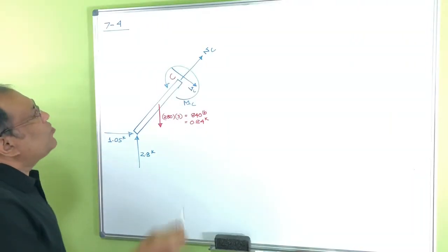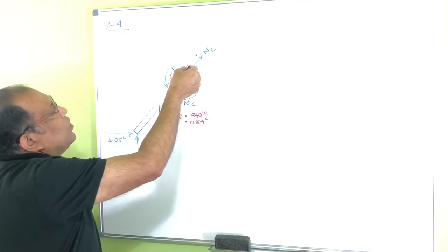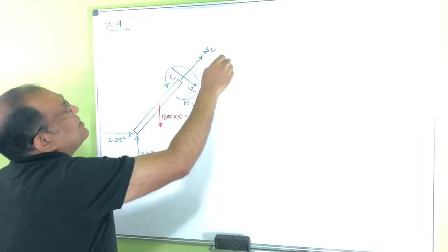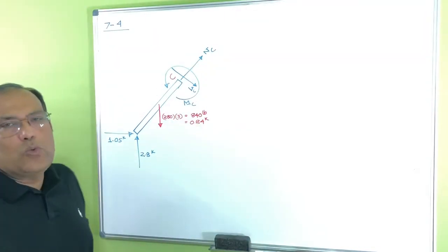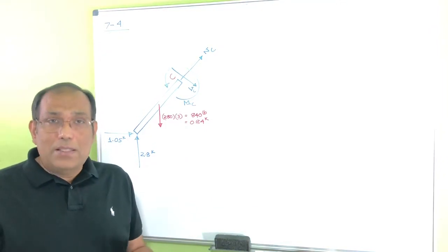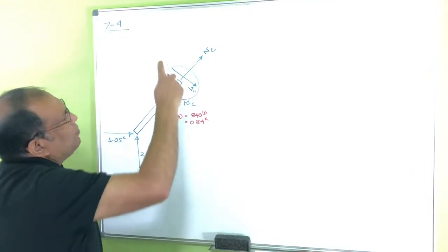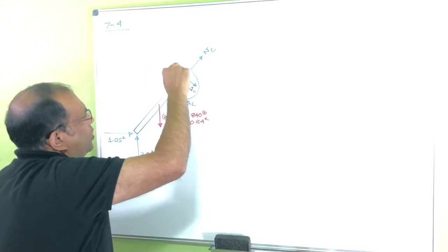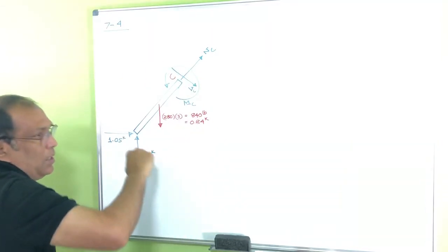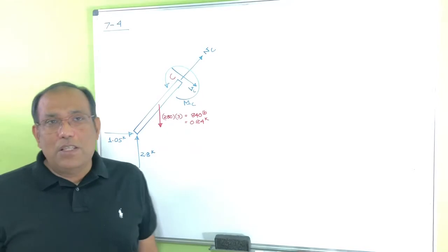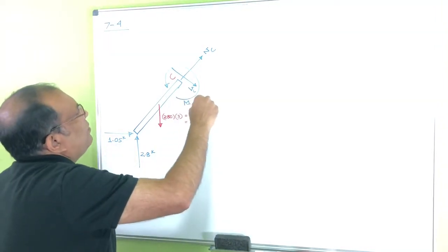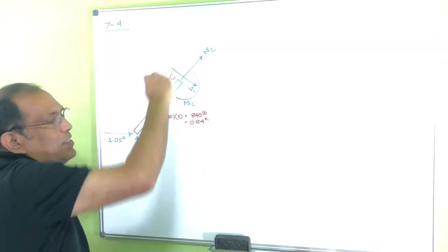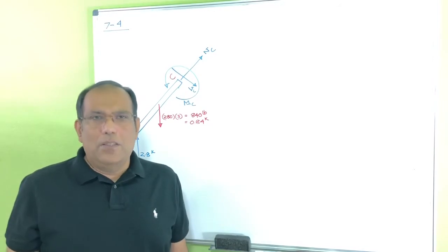You can see I'm assuming that the normal force working along the longitudinal direction of the member, this is at the beginning, I'm assuming this one is positive, means this is tension. Similarly, I'm taking the shear force VC, which is downward, so this one is trying to rotate that one clockwise, so it's positive. And then I'm trying to take the moment in such a way that this one makes a smiley face here, so this one is positive, right?